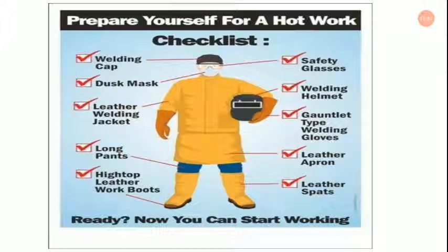Ventilation should draw all welding fumes away from the work. It may be necessary to wear an approved respiratory device if sufficient ventilation cannot be provided. As a rule of thumb, if the air is visible, clear, and you are comfortable, then ventilation is probably adequate.